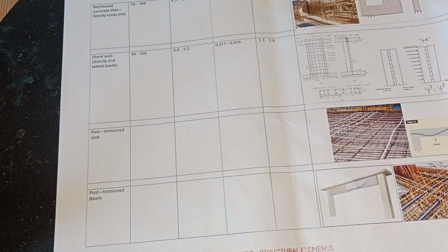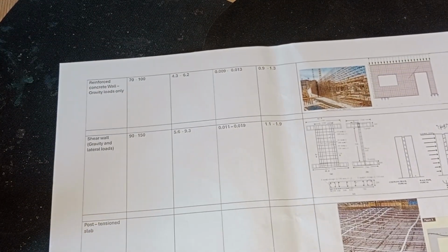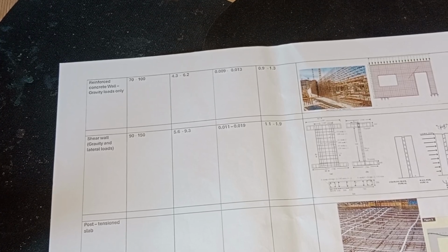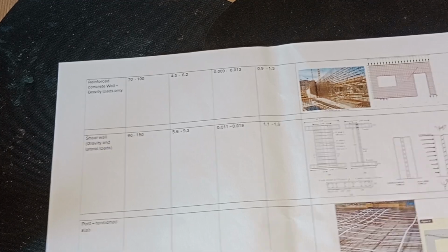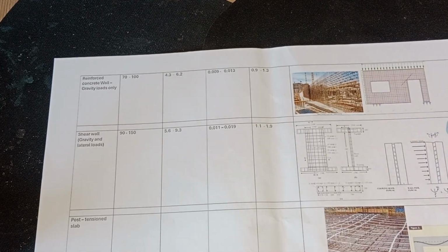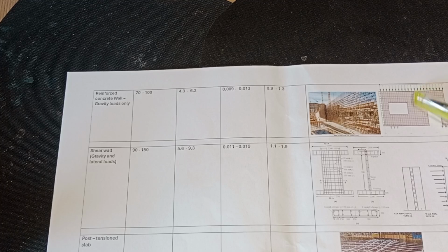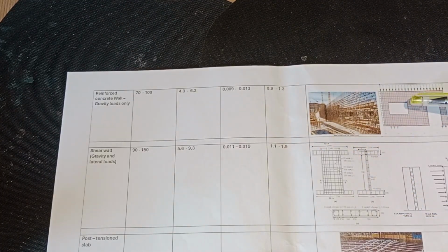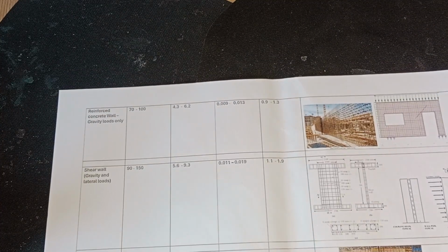The last page here is shear walls and gravity walls. For gravity walls, I would say that it is very rare in reinforced concrete design. We are going to have bigger reinforcement in shear walls, and it is very rare to expect walls taking only gravity load. In general, we have gravity plus lateral loading, but anyway, if it is used just for gravity loading, let's say 70 to 100 kilograms of reinforcement per cubic meter volume of concrete is enough, and it is good design, and the ratio is 0.9 to 1.3%.